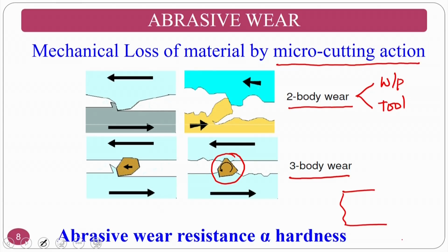Now the same thing, if we want to explain it from the point of view of metal cutting. Whenever you have a single point cutting tool where a chip is forming, and you are putting on a cooling fluid, what will happen? Because the chip is at high temperature, it will be in a semi solid form, and the chip is continuously flowing, because of which the tool gets hotter and hotter. In that circumstance, it may create some particles. This is in the semi solid state. Whenever a liquid with a high convective heat transfer coefficient falls, it may generate particles. There is a chance, I am not saying it is compulsory, whenever you are machining low melting point materials like aluminum. There may be a chance of particle formation because of the cutting fluid.